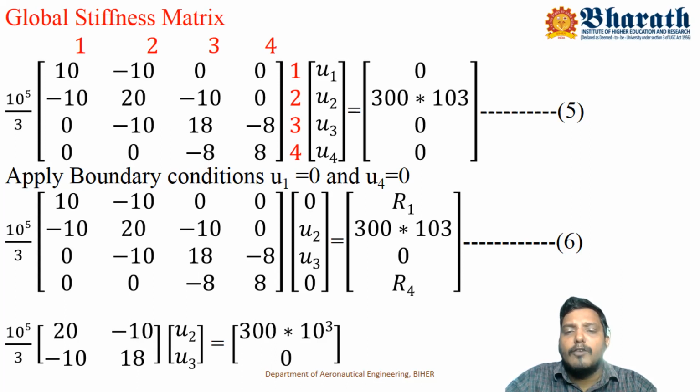Therefore, nodes 1 and 4 are to be fixed. They will offer reactive forces where the respective displacement is 0. This is an essential boundary condition, because at the boundary we specify boundary values in terms of your field variables or dependent variables. Here our ultimate aim is to find the nodal displacements at the respective nodal locations.